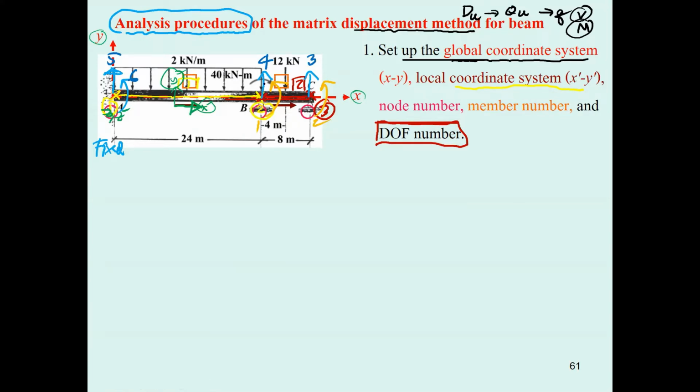Now we come to the next one. The load applied to the beam is not at nodes 1, 2, and 3. The load applied to the beam is along its length. Previously, the loads that we defined, Q1, Q2, that is Q sub K, occur at the node. That means you have to convert the uniform load and the point load to be applied at the node.